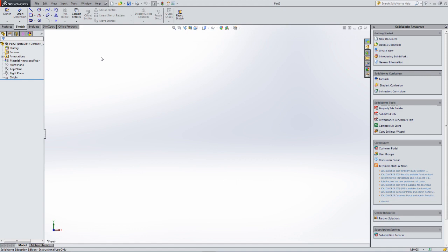We'll make that clear as we draw our airplane in this program. So, to start out, we want to draw an airfoil shape at the center line of the aircraft, our root chord, if you will, and we need to sketch that in a plane that is y equals 0 plane.